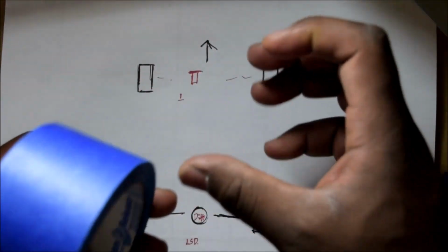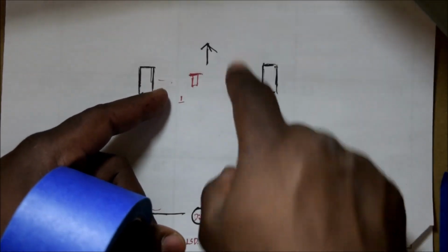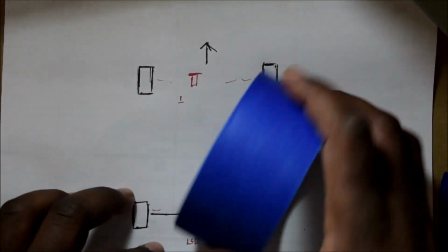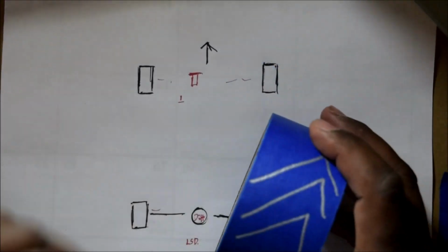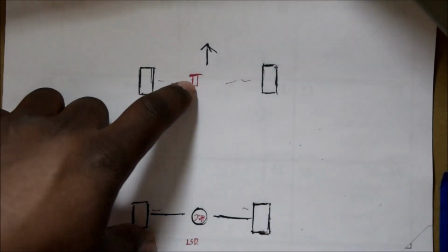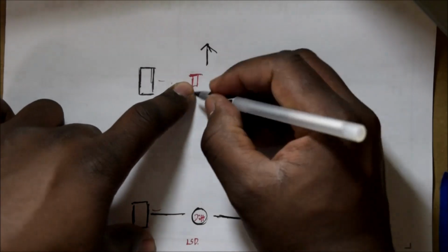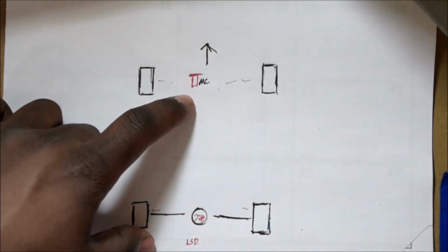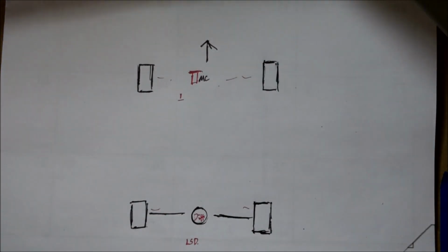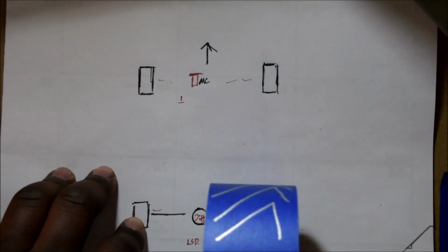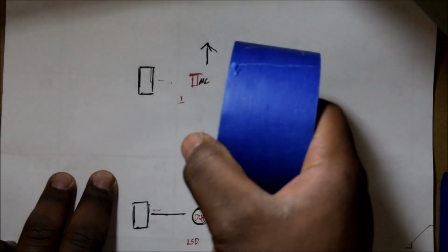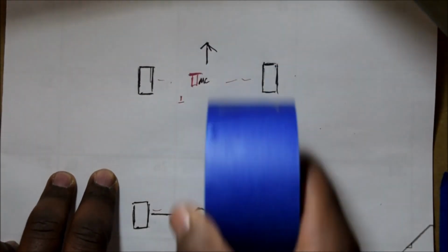Because at that point, all you have is those four square contact patches, right? Your wheel is not doing any rolling at that point. So the purpose of the ABS system, let's label this, by the way, MC for master cylinder, is to prevent that locking in a panic. What it does is it locks, releases, locks, releases, locks, releases.